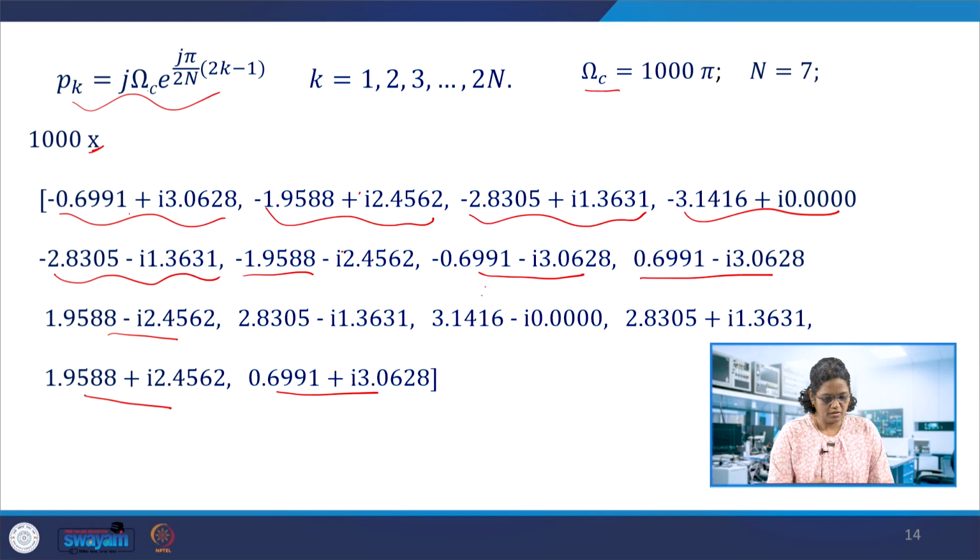So these are the pole locations of the filter which has the characteristic of Butterworth. It exhibits a maximally flat response and a monotonically decreasing response in the stop band, with the allowed ripple being small over here. This is one design of the Butterworth filter. After getting these poles, you make the factors s minus each pole and multiply all of them, and you will have this polynomial, the denominator of H(s). So 1 by that would give the H(s), and after that you can discretize it.